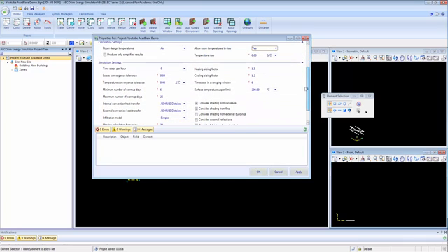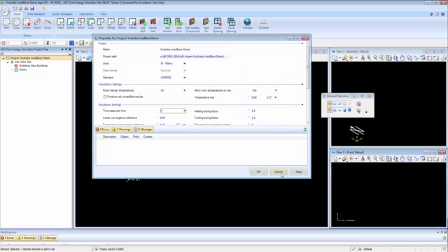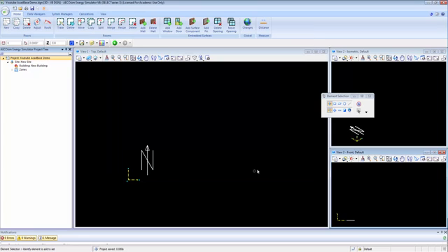And then here we have our settings for other aspects of the analysis itself. So time steps per hour, 6 per hour, which is every 10 minutes. So let's drop that to 4. Heating sizing, etc., etc. So you can read through on all these things. So there's again a bit of confirmation, a few little changes, and then click apply, click OK.